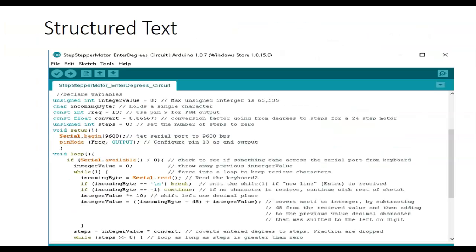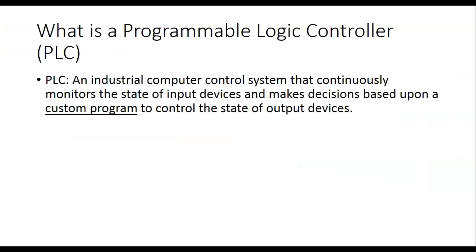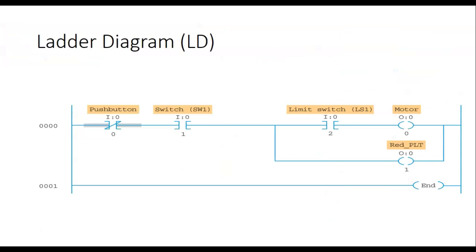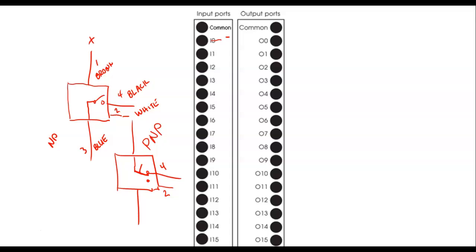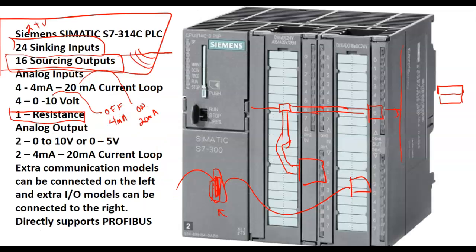From your point of view, sinking and sourcing is very, very important. Knowing how to run the application so your PLC can help you troubleshoot. Also, another thing we need to understand is the PLC has indicators on the front of it. The PLC has all these light emitting diodes that show you when an input gets to the PLC.